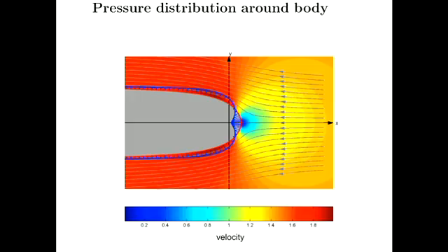Can you see that the pressure distribution on the upper and lower surface of that half-Rankine body is symmetrical? It doesn't really come as any surprise because the flow field's symmetrical. So in a net sense, there's going to be no force acting on that body in the wall normal direction, right? Because the pressure forces on the upper and lower surface are just going to cancel out.